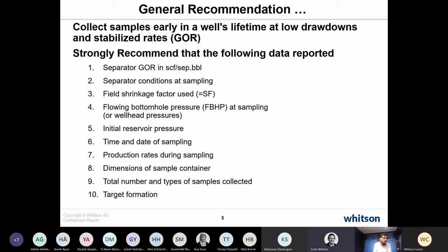Curtis? Yeah, the water can be very important, of course. If it's in situ water, it can be because of the compressibility effect on the material balance, the rate of pressure decline in the reservoir, getting the compressibility right. If it's water injection, getting the viscosity right. In gas reservoirs, the water might conceivably contain a lot of H2S, CO2, methane in solution.